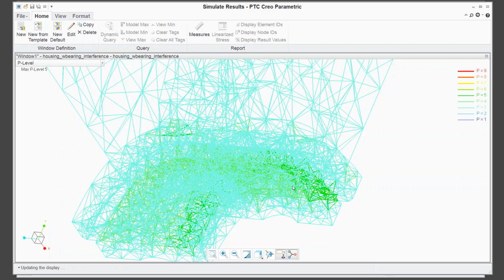And we have effectively done mesh refinement on the fly without having to do mesh refinement. Because the alternative would be to go in and tighten up the mesh on those regions where we put small mesh to begin with, and the solution time would probably double if we were to do that. So we've effectively accomplished mesh refinement without doing any work and without excessively increasing solution time. And that's what these elements are. They are good at taking mediocre mesh and turning it into a really good solution.